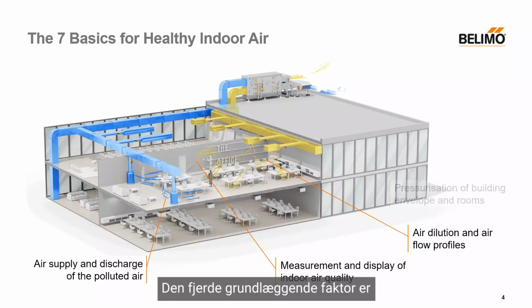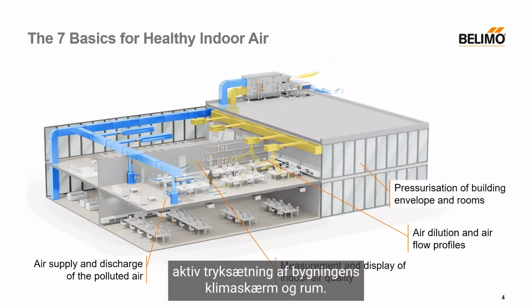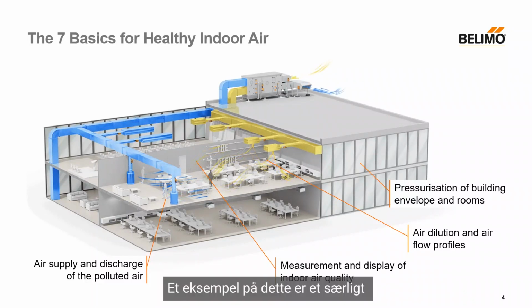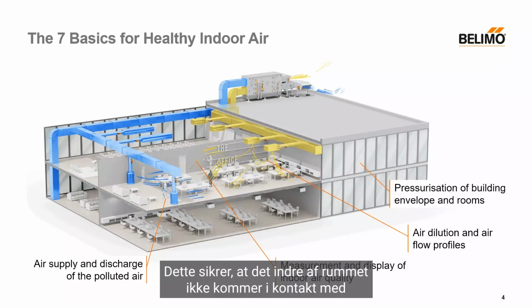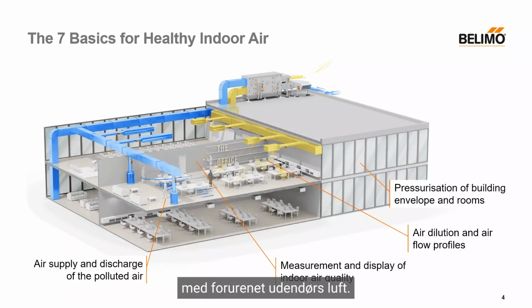The fourth basis is active pressurization of the building envelope and rooms. An example of this is a special operating room in which gauge pressure prevails. This ensures that the interior of the room does not come into contact with contaminated outdoor air.